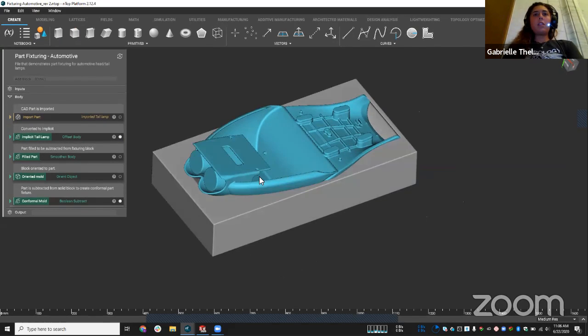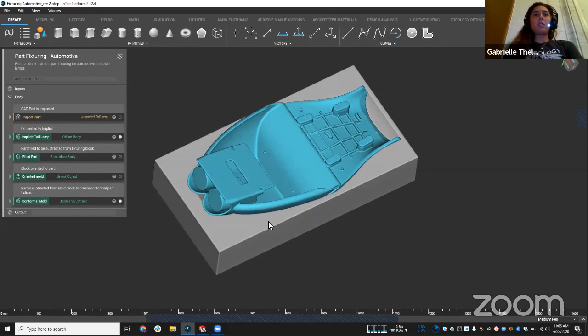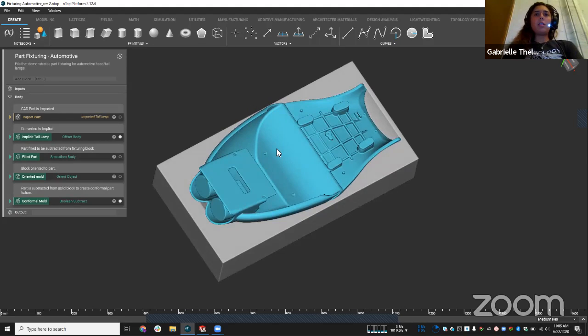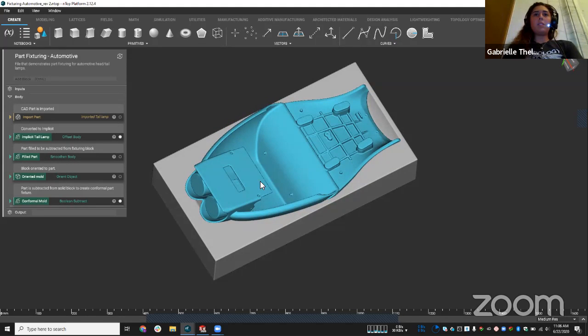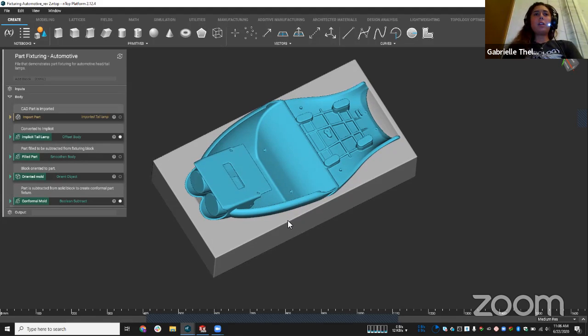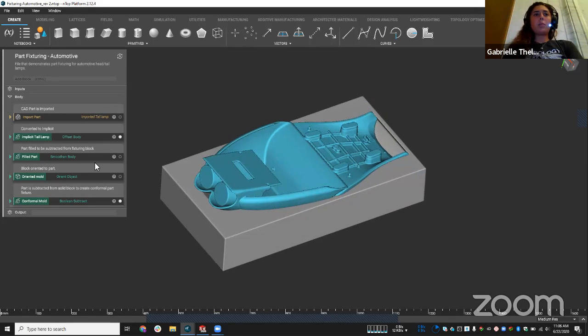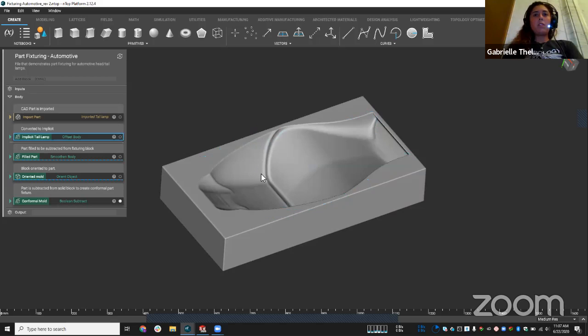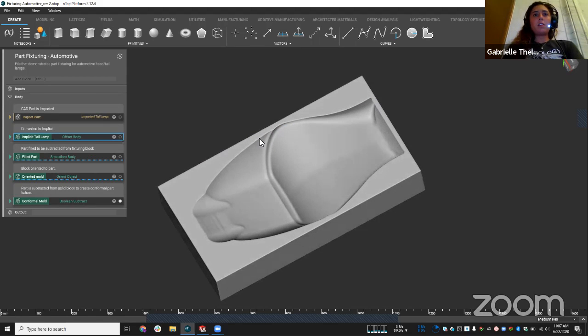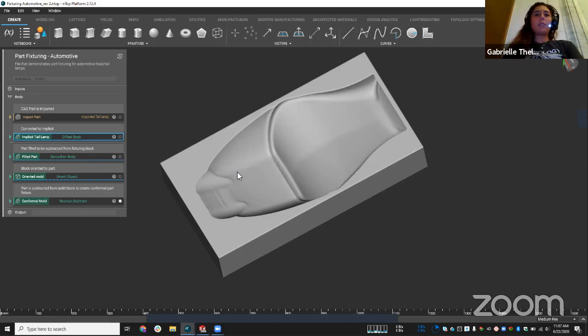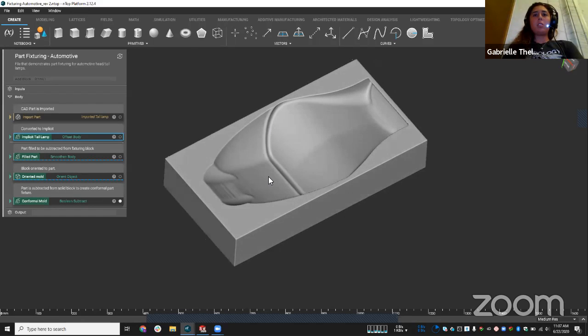I've got another one, this is actually the back of a motorcycle, but still a tail light. You can see these different tabs here, and these are the tabs I was talking about that involve welding in. But again, we have this more complex part. I'll remove that view and you can see we get a nice conformal part fixture here, with nice rounded areas conforming nicely to ensure that it's secure and that the outer surface is not going to get damaged or scratched.